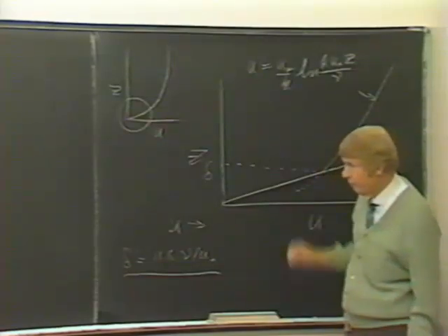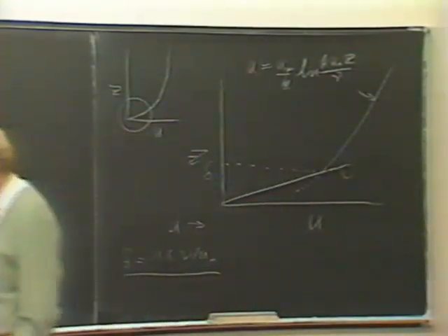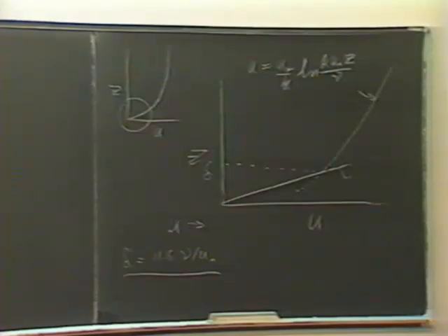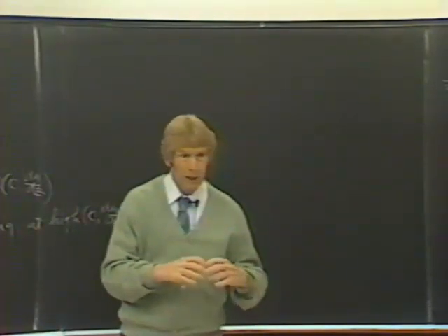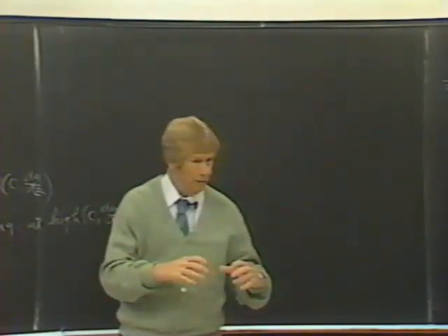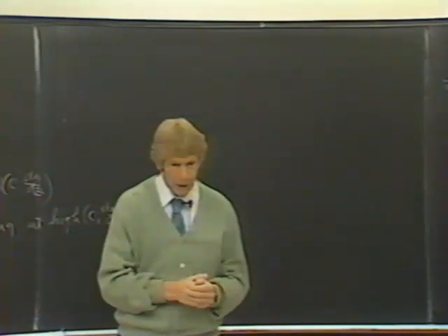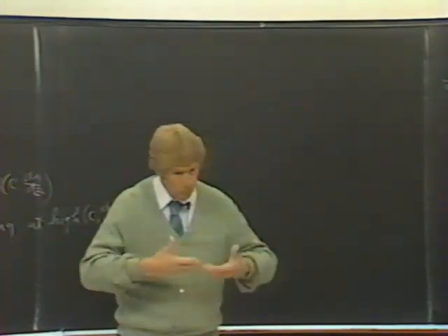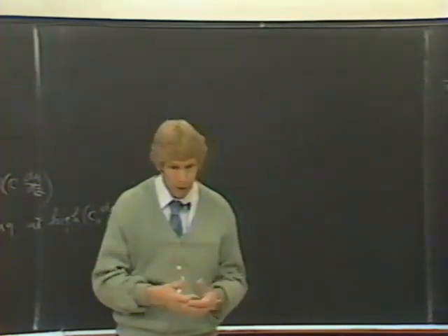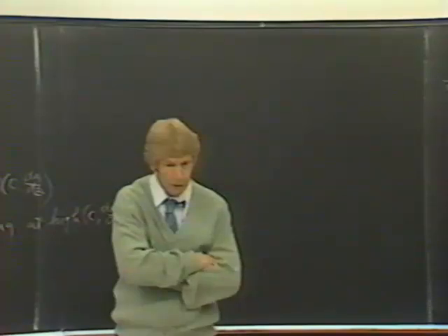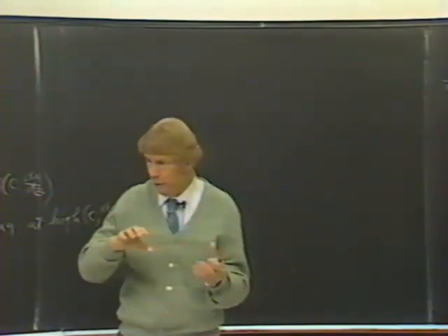In a channel, it would just be the depth. We'll notice that while there's more scatter than there was in the previous one, it still looks like a linear relationship supporting this description of the probability that the particle sticks to the bed. This is a different sediment, so the tau critical, the intercept with the abscissa, is different. This is about 0.8 of a dyne, I think, per square centimeter. But it's not that much different.